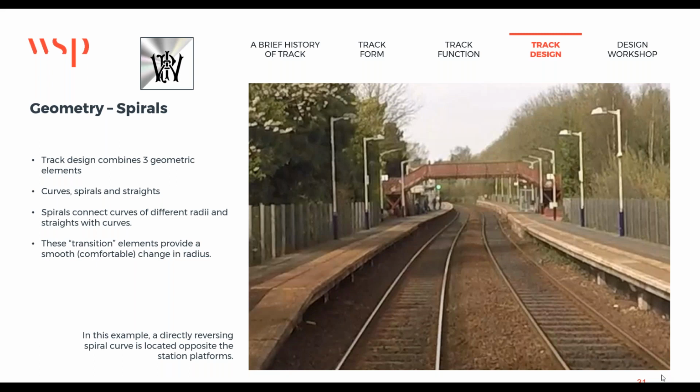And I put it to them that actually what they should have is a standard that says, thou shalt consolidate the subgrade, thou shalt lay your fine separate or whatever else you're laying, and then you shall compact your ballast in layers up to sleeper soffit -10. And that's the way I used to do it. And I don't see why everybody can't adopt that and forget ballast ramps. But it will remain canteen chat unless more people start challenging that standard.